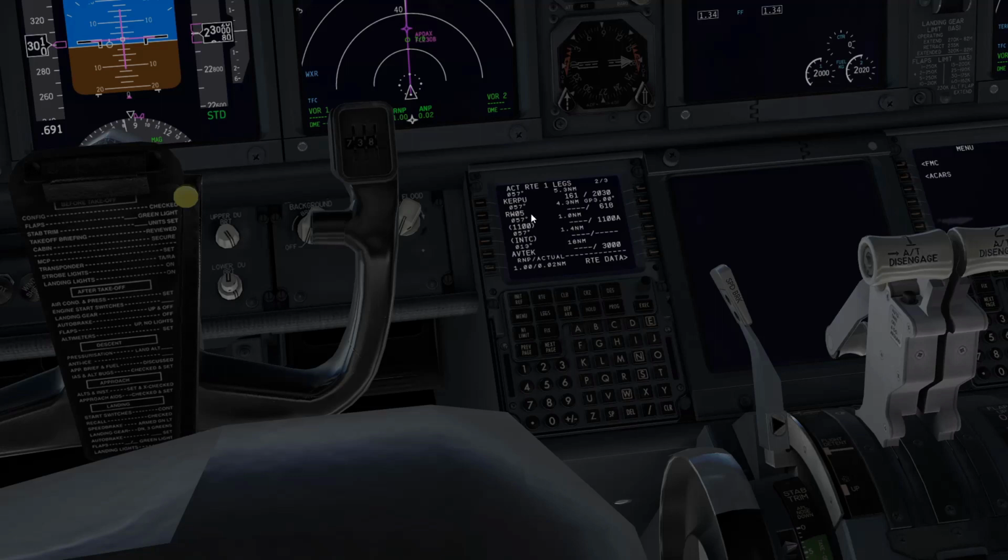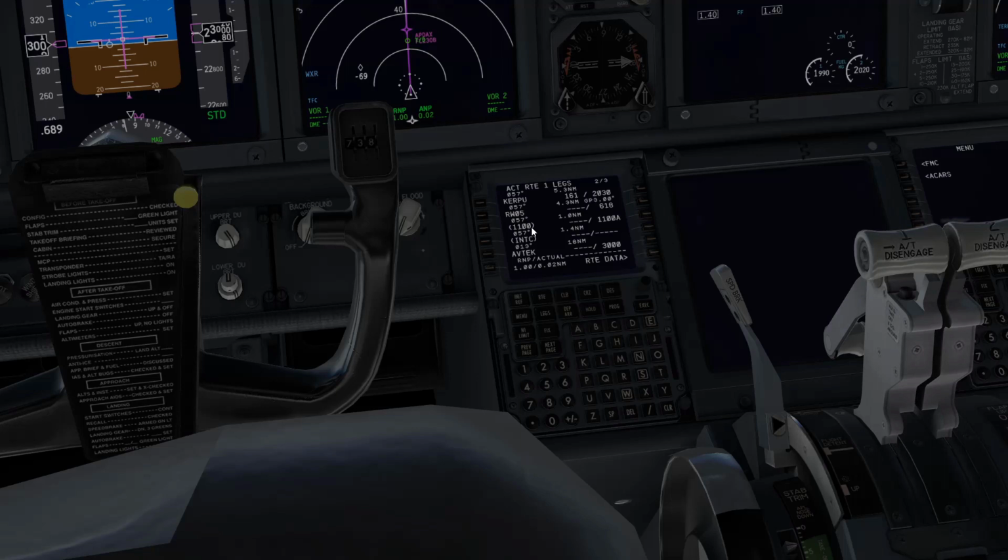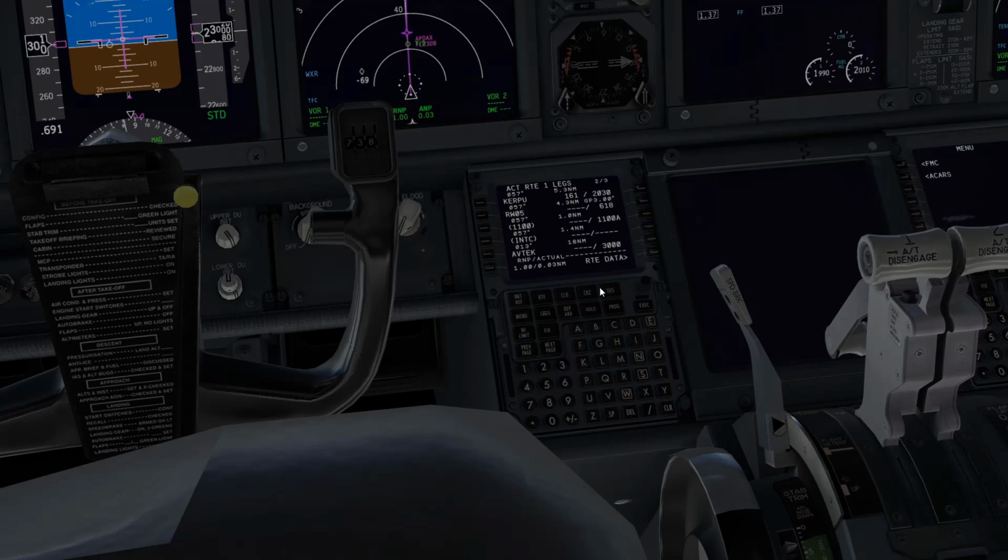And KIRKBU, runway 05, missed approach 057 to 1,100 feet, 057 to intercept a 013 degree track to AVTEC. So basically it's a climbing left turn through 1,100 feet to intercept a 013 degree course to AVTEC, maintain 3,000. That's good. So we can use that.